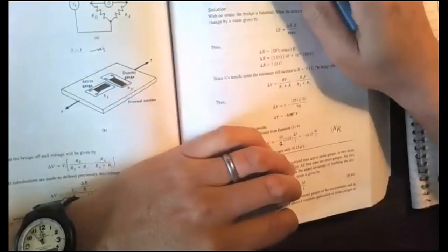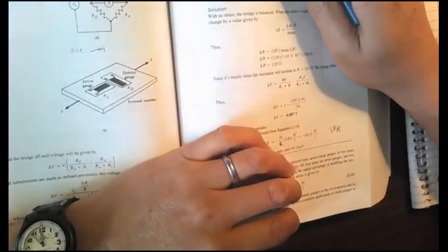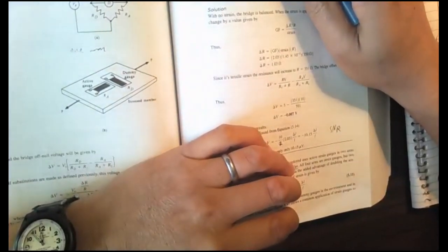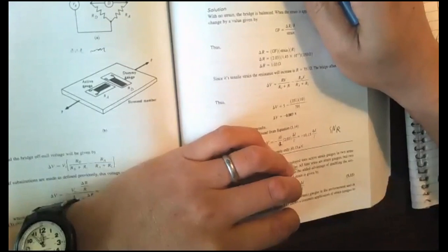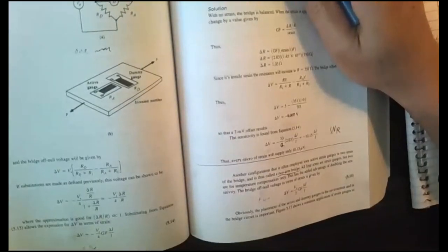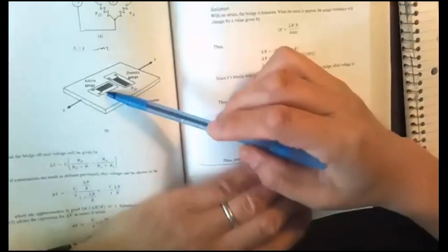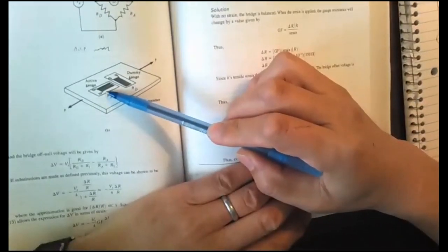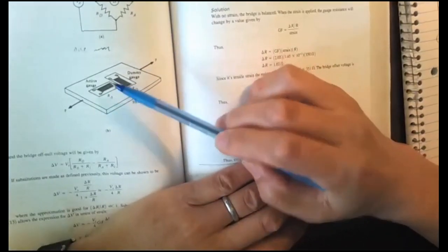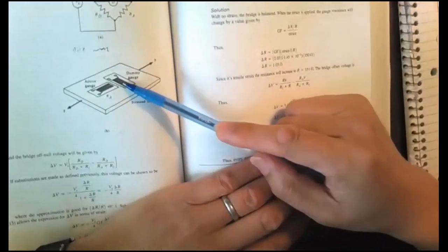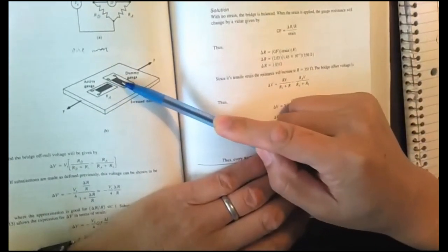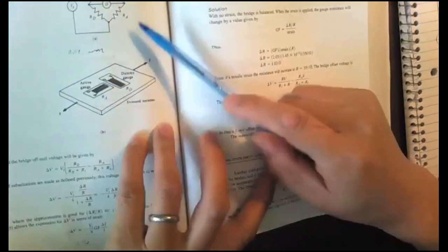That will be like you go to the gym in the summer, you weigh 200 pounds. You go to the gym in the winter, you weigh 150 pounds. It's not because you lost 50 pounds. It's because your sensor is messed up by temperature. So obviously you want the dummy to cancel the temperature effect.